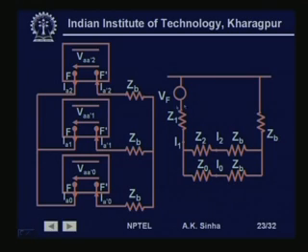So, it is open. So, when we reduce this circuit, we reduce it to this form; that part, 1 by 3 (ZA minus ZB), is no longer connected in parallel, that is open. So, this is the total circuit that we have, and we can calculate I1, I2 and I0 for this circuit.